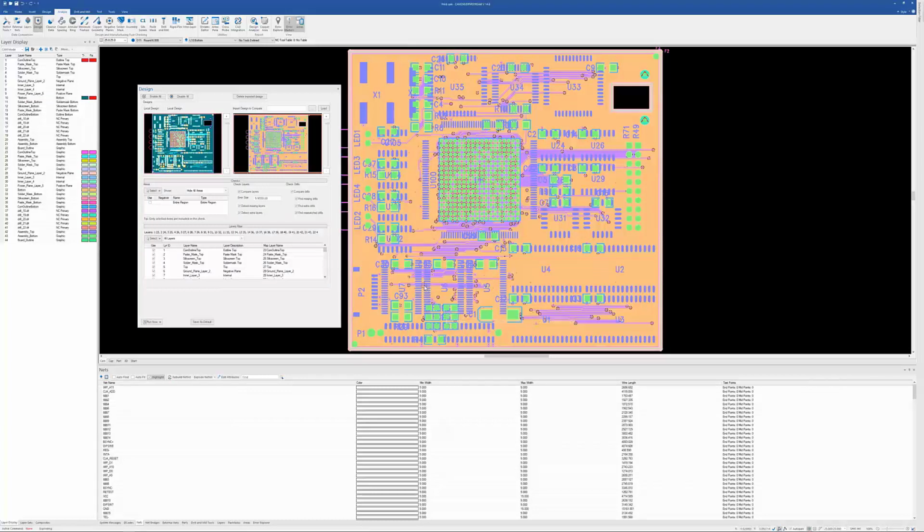If it's not registered, you'll see a difference here. If it is registered, you can just go simply to run it. There are some parameters that you can put in, and you can also map the layers here. So if your layers were not mapped automatically, you can manually map those layers. We do it by layer name.